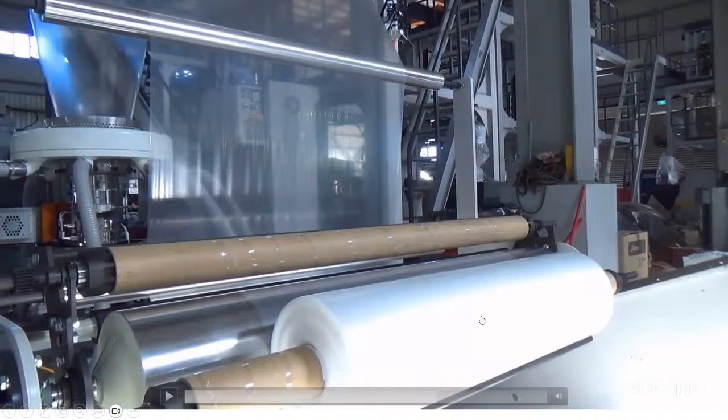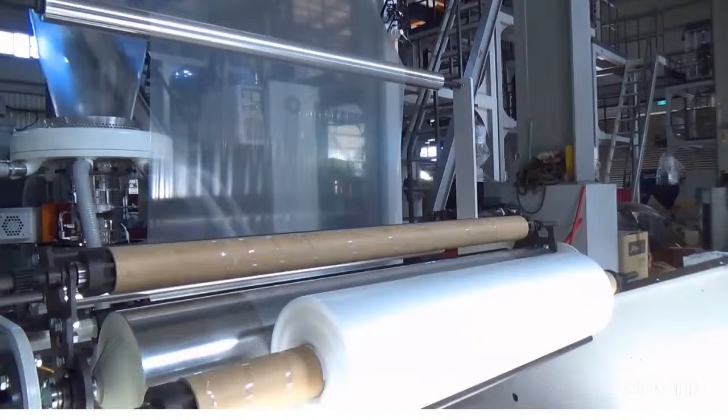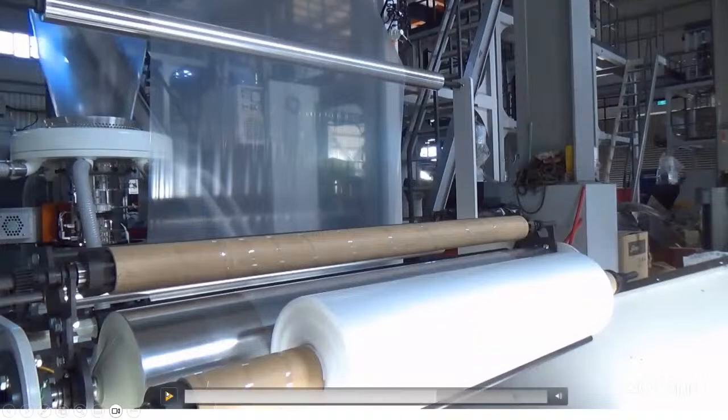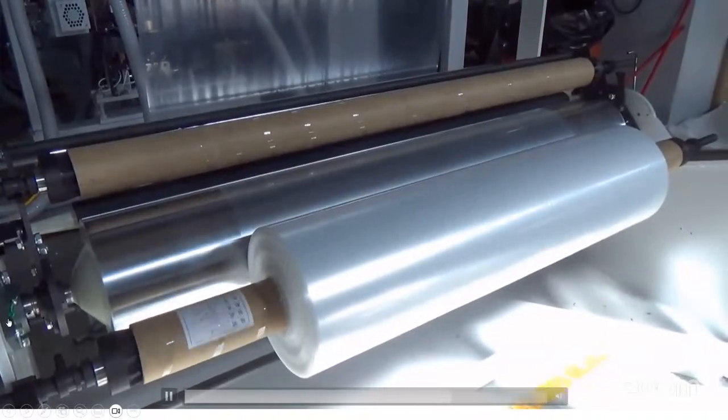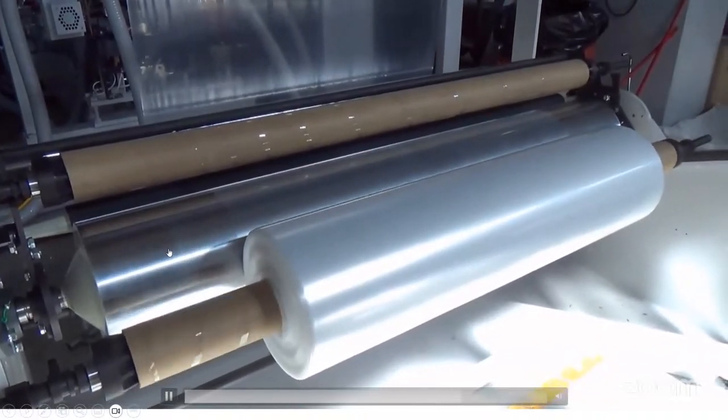People are using surface winding because here there is only one big roll, and around the big roll there are a number of bobbins, right? Now, after this, it will get shifted here. After this, it will get shifted there, right? You can cut this film easily. At how many meters you want, that can be wound here. Okay. So friend, this is a very unique plant. If you see now, only this roll is rotating. See here, the motor is there. And the bobbin is rotated due to this roll.